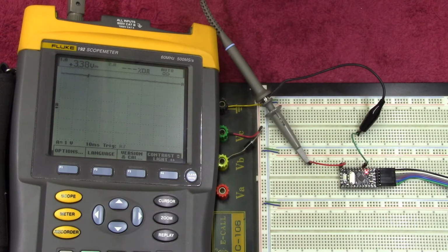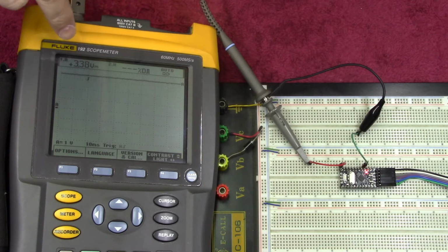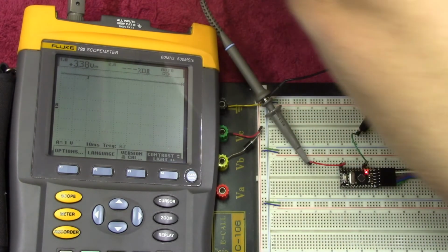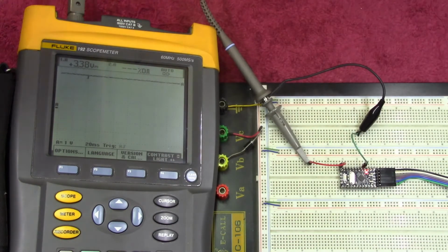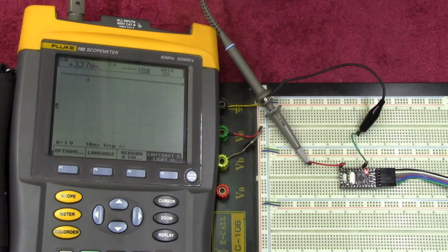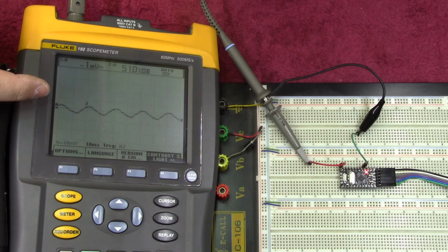Right, so what you're looking at here is 0 duty cycle, and you'll see 3.3 volts. We're at the maximum, and you'll see a flat line on that rail. Now if I was to run 127.5 on the Arduino, which would give me a 50% duty cycle, let's upload that. You'll watch it reset, and we'll see what we see here on the oscilloscope.